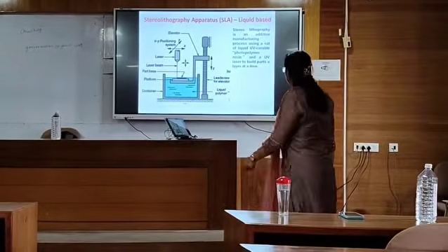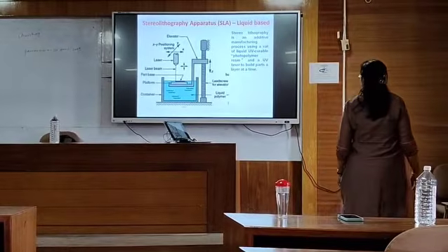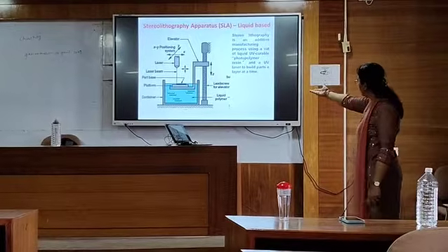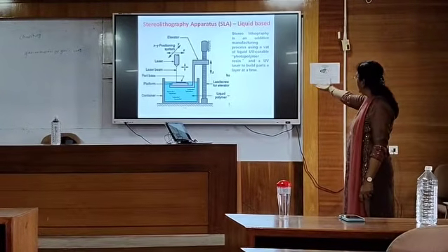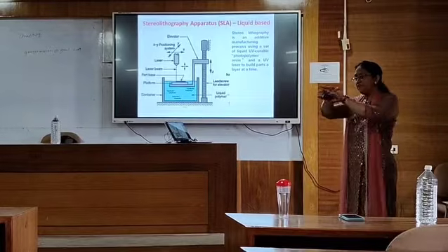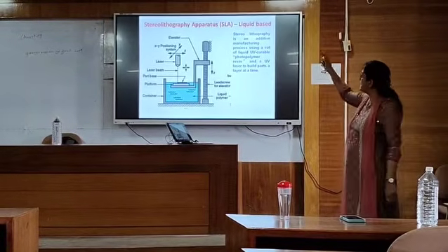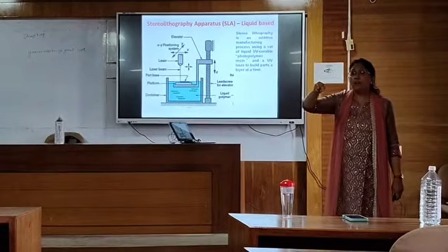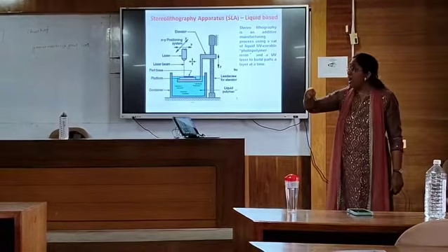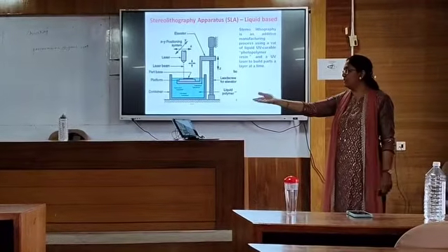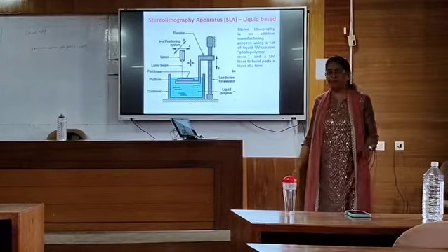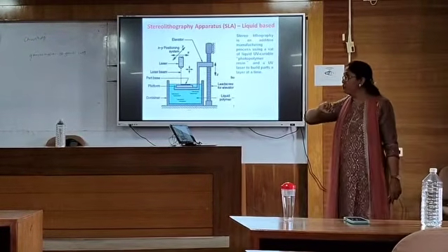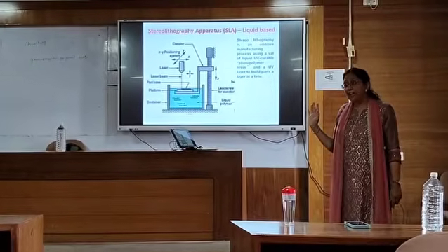Fine. So here you can see the vat. Vat means the container. Under this, the liquid resin is available to you. One bed is there attached to the elevator. Initially, the first layer will be generated when the laser light comes in contact with this liquid. Now your laser light will move as per the 2D geometry. Just now we discussed how that 2D geometry will be created for every layer. So as per that 2D geometry, the laser will move and create a solid layer.